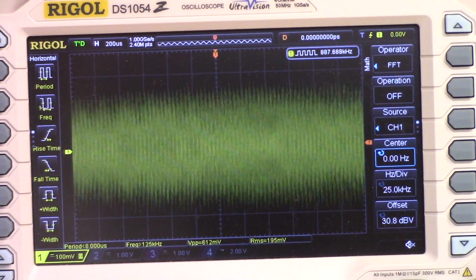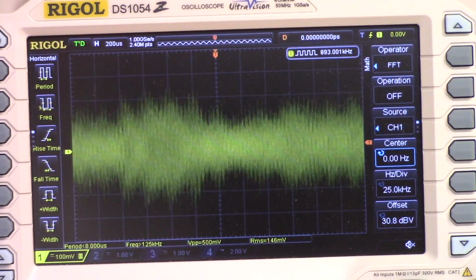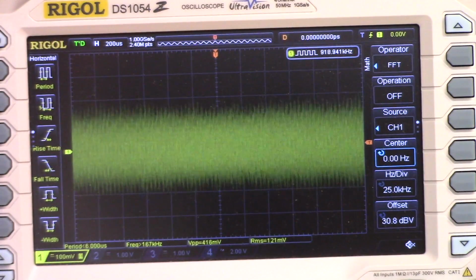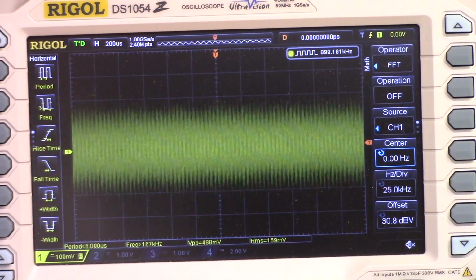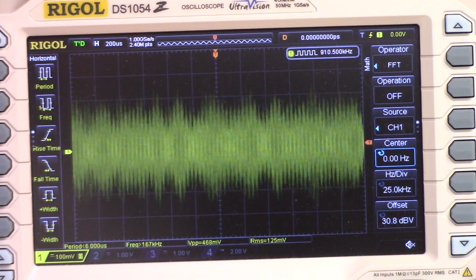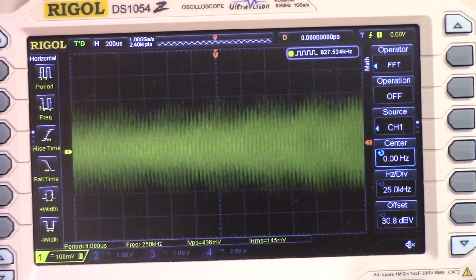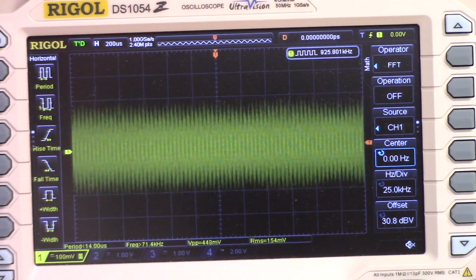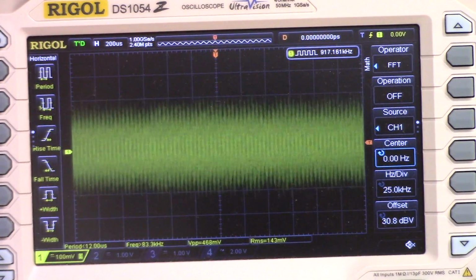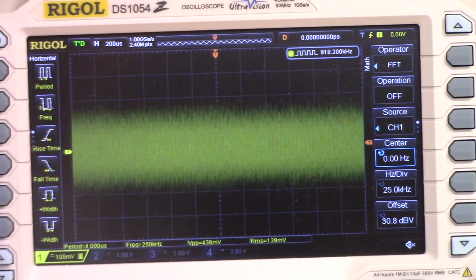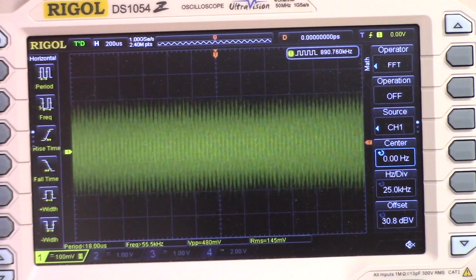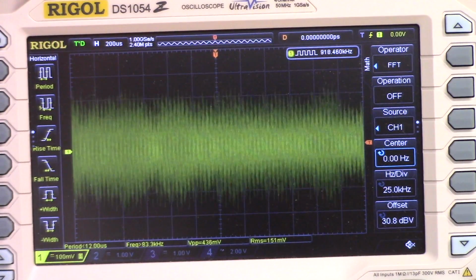Sometimes when an announcer pauses on a radio station that you're listening to, you will see modulation in the signal on the oscilloscope. And the reason for that is because we have no sharp resonance in the loop antenna as it's currently constituted. Or to make that even more clear, the signal that we're seeing on the oscilloscope is actually the sum, or a superposition, of signals that are radiated by all the AM radio stations in the area.